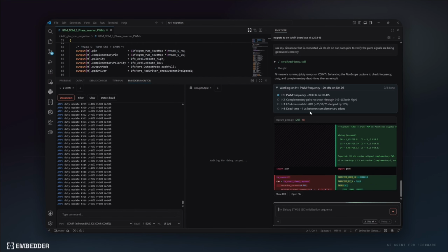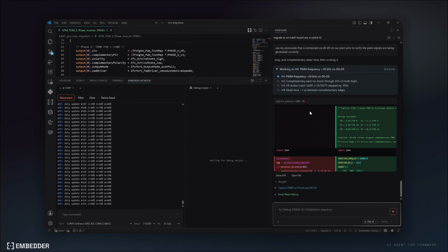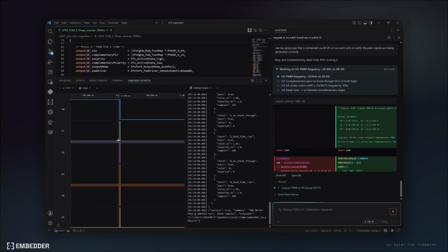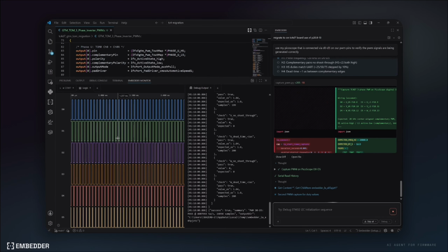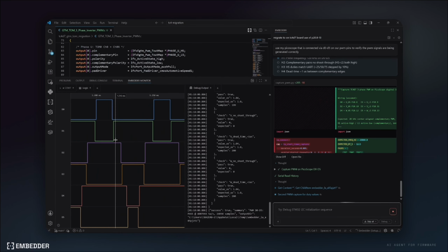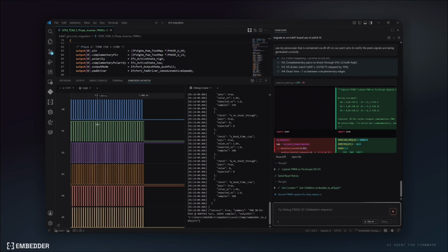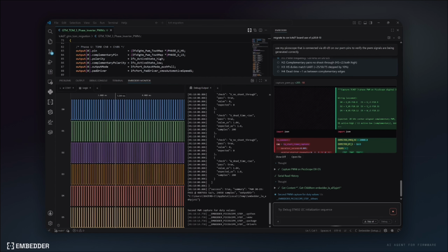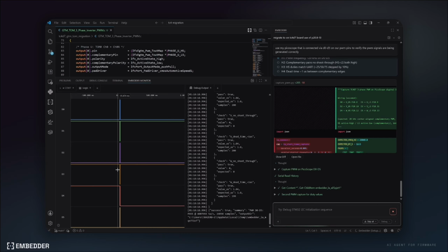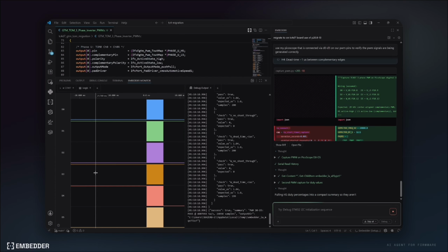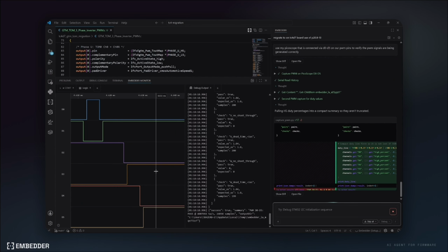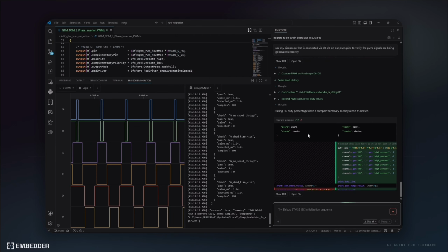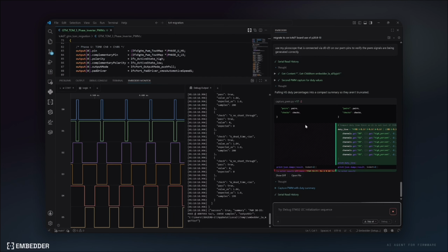Okay, so we have written our PicoScope capture, and now we are running our capture. We can see our PWM signals here, which have been correctly generated. And we can zoom in. This applies to oscilloscopes as well and other test equipment where you can see outputs. It's all integrated within the IDE, which is great, and you're able to get this visualization. This is what we're seeing.